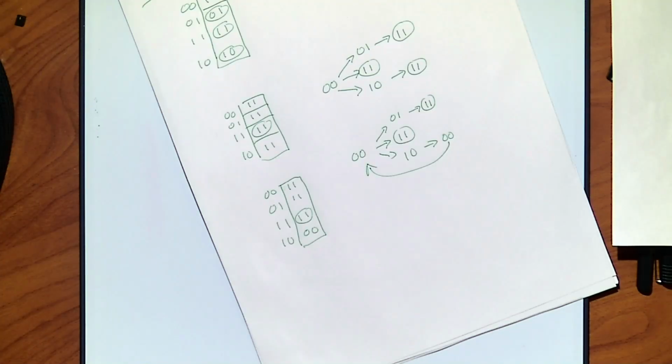This is bad behavior. So one of the things we're going to want to do with a lot of these is how do we recognize the problems? This is a big, big issue to us in async that we didn't worry about a lot with other things because they were already nice and safe. You couldn't get stupid fast races. Even if there was a slight difference between them, I waited until an edge happened, so there was more than enough time for both things to have transitioned. I never sampled it early. Now you're sampling it early, which lets these races happen.